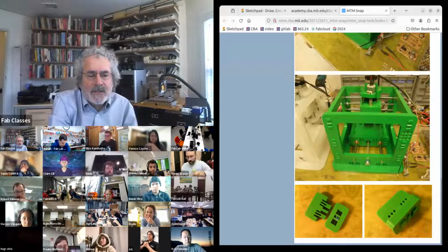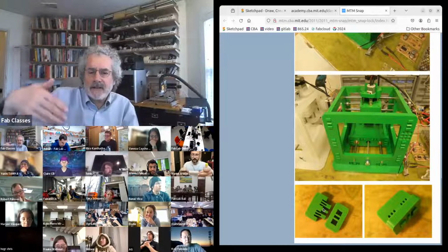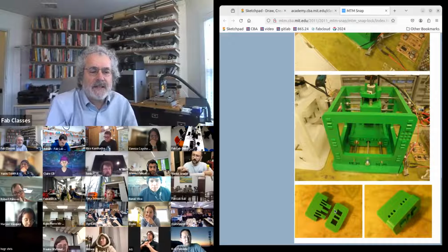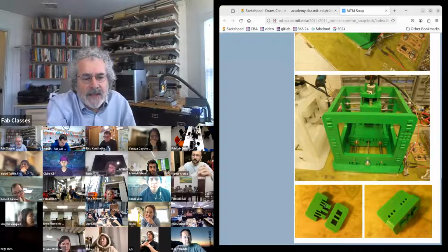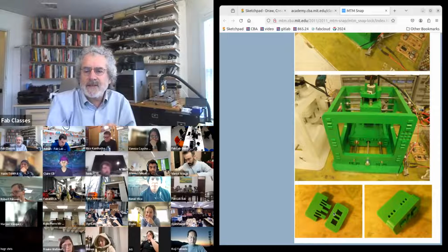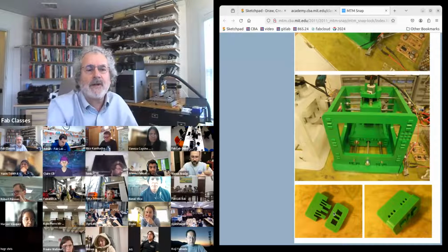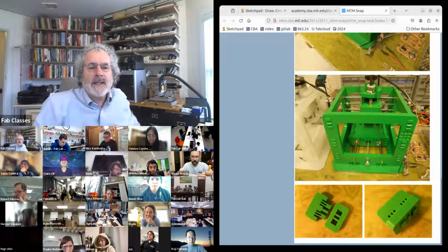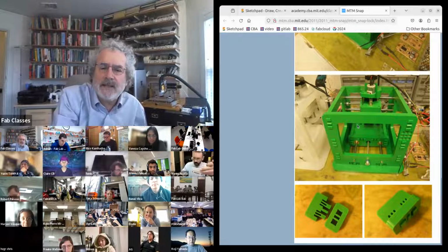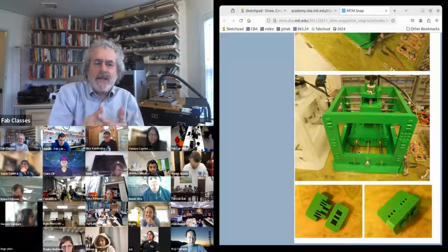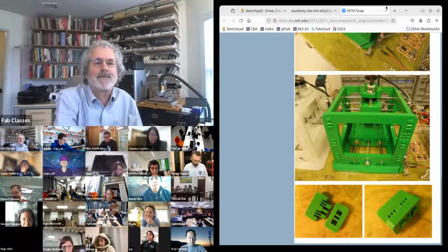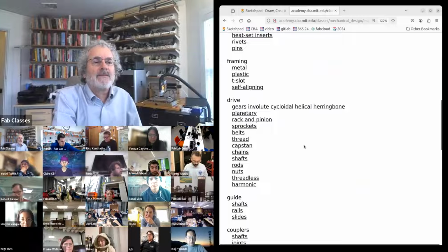The center tab goes in. The shelf there controls the depth that goes in. These feet constrain it. And then these flexures go in and constrain it from the opposite side. So the whole thing snaps together in a very tight joint. And so there's no alignment in the machine. When you machine the HDPE, you put in the places for the attachments, and then you just snap the whole machine together. So that's framing.